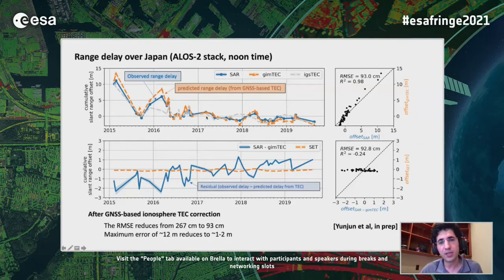And then by time it gets down. We took ionospheric products from IGS, which is every 2 hours, and we already got some good match with what we observed in the SAR data. So indicating that really, as we would expect anyways, the main source of the delay is the ionosphere.